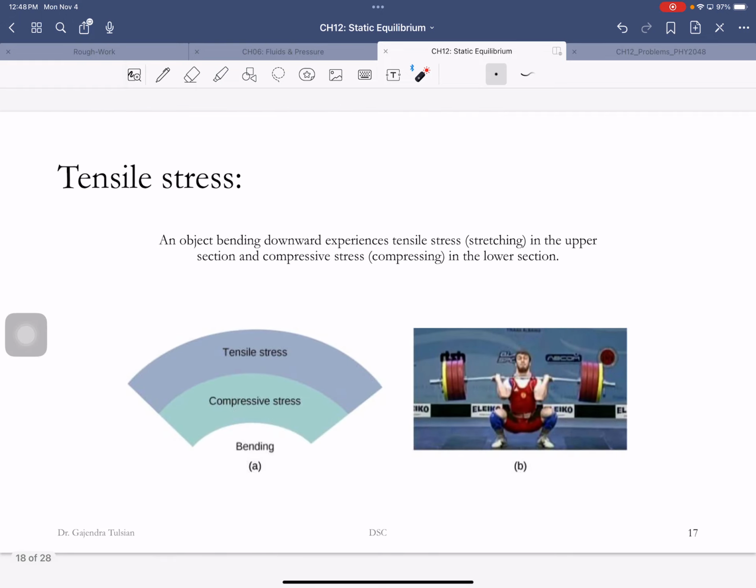All right, you saw that if this rod is made of cast iron, it's stronger under compressive stresses than tensile stresses. So if this rod were to crack, it would crack somewhere there. It never cracks there, unless of course it's defective at the bottom.